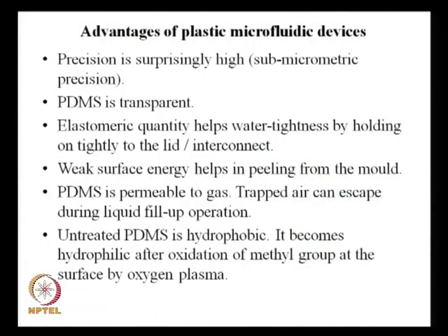The next point is PDMS is permeable to gas, so trapped air can escape during liquid fill up operation. This PDMS material can permeate a gas. When you start working with your device, suppose you fill the channel with a liquid and the channel is occupying some air. Either you have to apply vacuum so that air comes out and liquid gets in. So, you have to make some arrangement to have the liquid penetrate into the channel.